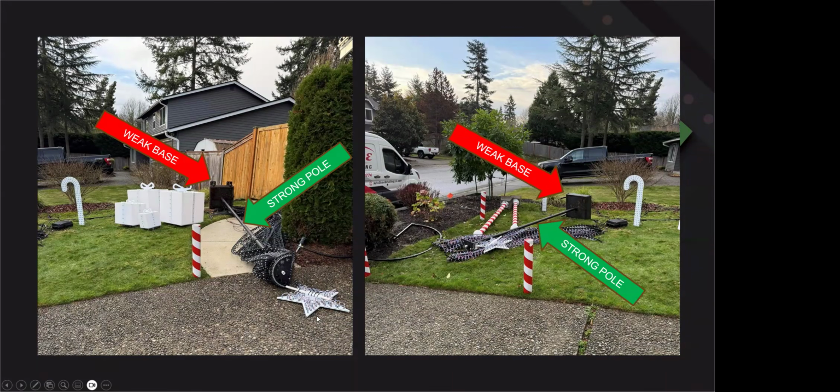And as we mentioned before, the star here laying on the ground looks like it was probably connected in here. Big sail pulling this whole thing over, catching all of the wind. Your base is very often the weak point in there. To make up for a weak base, you either need to put more concrete in here, make it bigger, make it wider. That'll help it from tipping over. Or as I have mentioned and will keep mentioning, guy wires always help these type of things out. When you're going against Mother Nature, it's tough to win the battle all the time. We're not always going to win, but you want to do the best job that you can.